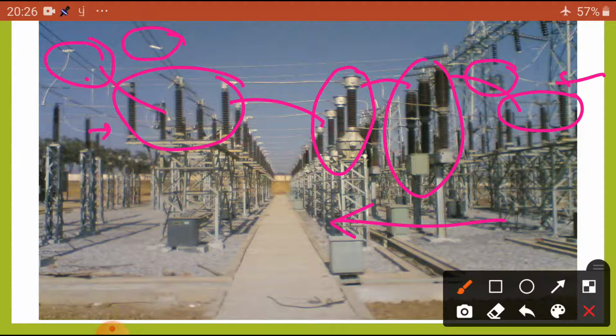Physically we can see whenever the isolator is operated, opened, it is automatically connected to the earth switch. So whatever the induced charging current, that is diverted to the ground. So the operator can easily repair any equipment. That is the purpose we are going to use the isolators. Next, these are the bus bars. So we can see this system in our single line diagram.